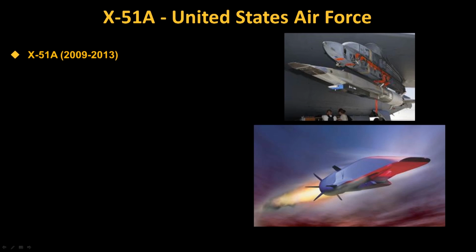The X-51 flight program was organized in a similar fashion to HyperX, with an air launch and a rocket boost. However, its goals were quite different. Rather than going for a short test at high Mach number, X-51 was aimed at sustained flight using liquid hydrocarbon fuel. Sustained flight requires the use of lightweight materials that can withstand high temperatures. As heat loads increase significantly with Mach number, the modest Mach 5 flight of X-51 simplified materials issues.